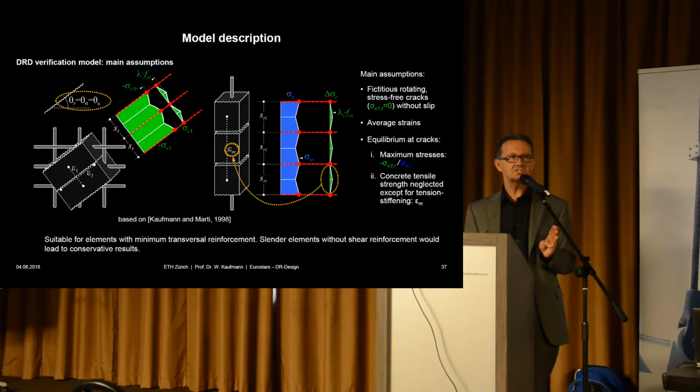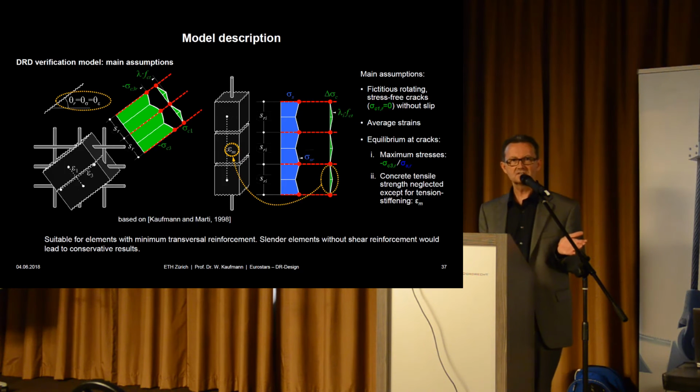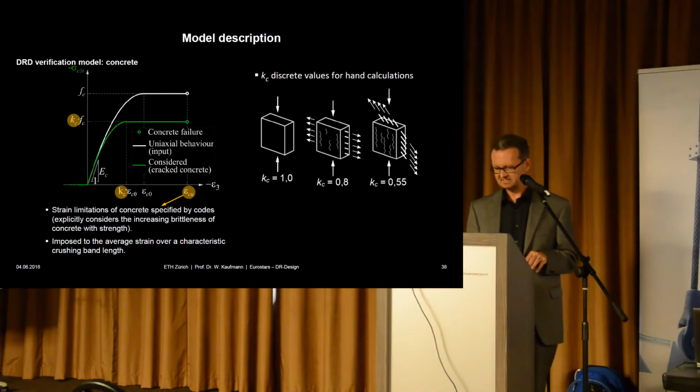It's the average strain, or the integral of the steel strains over the length divided by the original length. That's the average steel strain, and not the maximum one at the cracks. So this is how I get a stiffer behavior, which helps in reducing crack widths. Okay, then here again, you can see that also. And this assumes minimum reinforcement. I will show that on the next.